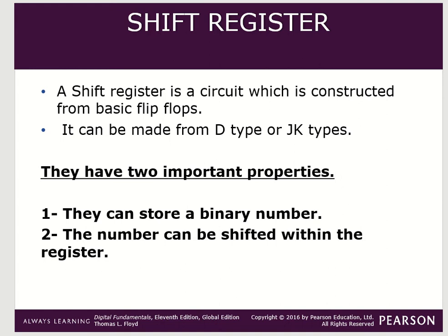According to the definition, a shift register is a circuit which is constructed from basic flip-flops. So it means that a shift register is made up of flip-flops. We already studied basic flip-flops last week and before that also. We studied SR flip-flop, JK flip-flop, and D flip-flop also. A shift register is basically made from either D type or JK type.